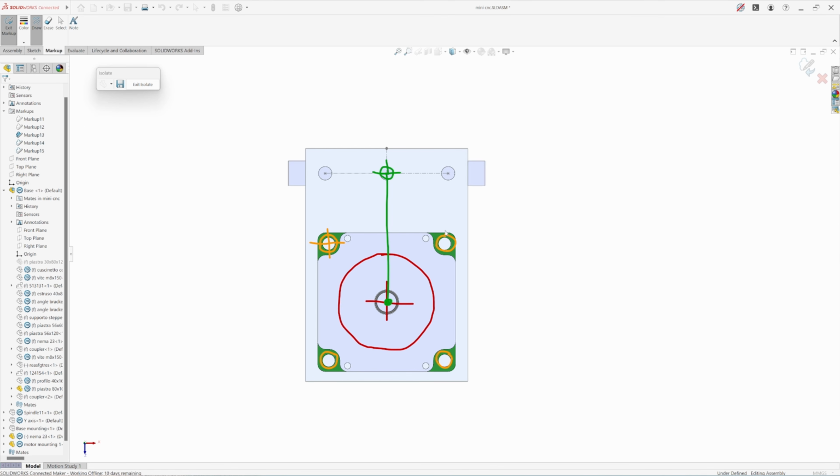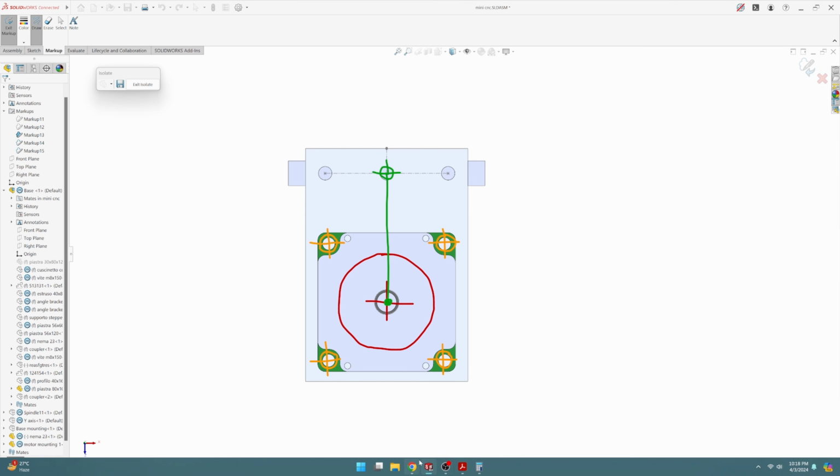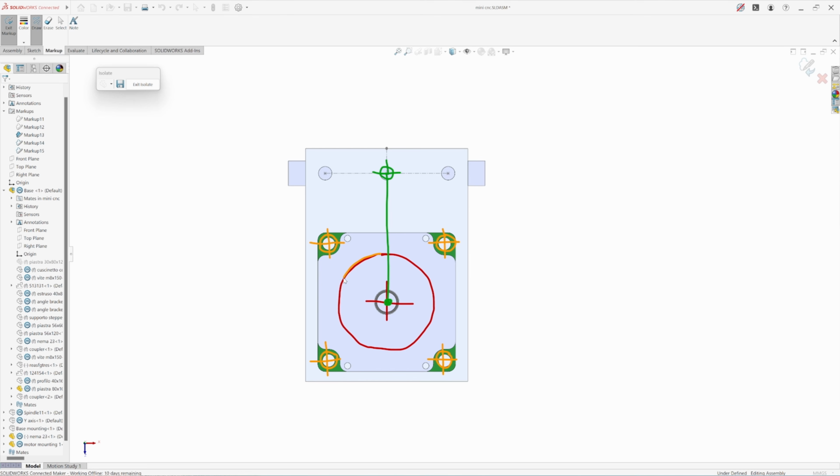Next, these 4 mounting holes of this motor. I would like to control these 4 mounting holes with respect to the motor guiding step hole, neither from any side of the plate nor from these plate mounting holes.